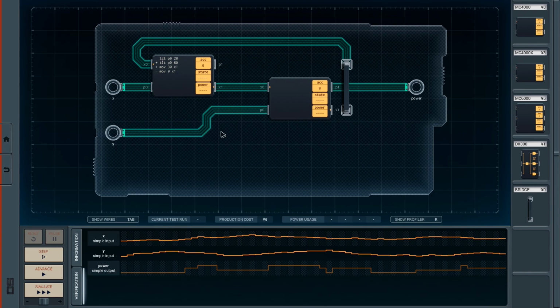Okay, now we need to do the X test for the little hotspot section in the middle, and we're going to send the result of that along X0. Looking at the diagram, it has to be between 40 and 80. If it's between those values, it could potentially add 50 to my output. However, it would still have to be in the Y range. So we'll do that, and if both of those are true, we send a signal on the X0 bus. I guess I can just send 50 along. Maybe I can use that result. I guess it doesn't matter because the number isn't going to be relevant. It just needs to be low or high.